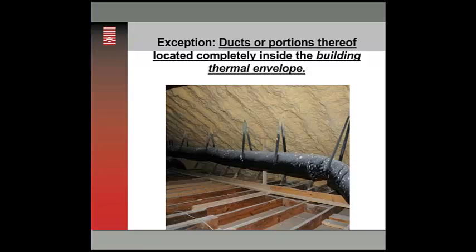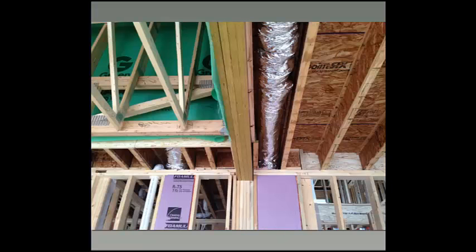Are ducts totally inside the envelope, or are there areas where I'm running some of my ducts from the inside running out? I think the trickiest questions that we're getting have to deal with bonus rooms, tuck under garages that have a living space above it, or cantilevers, or ducts that run from the first floor to the second floor in outside walls. You really are going to have to work with your local official to come up with guidance on that.